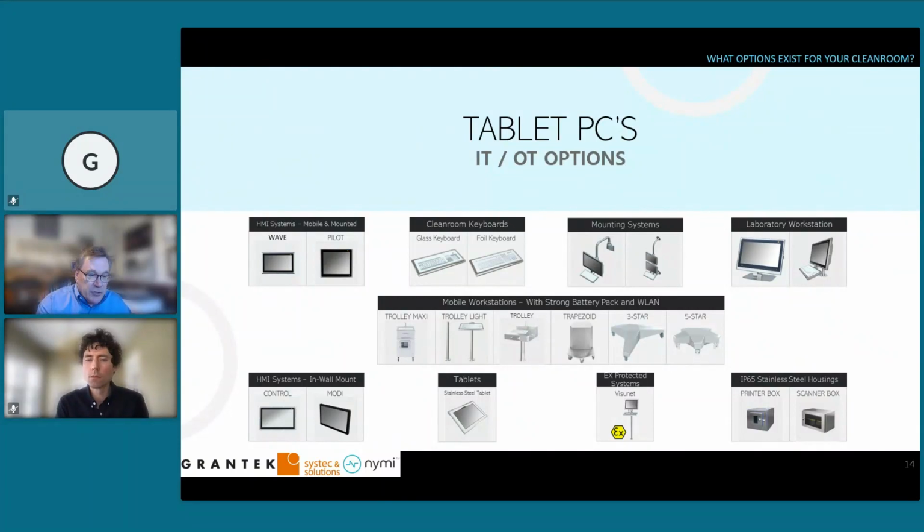First, you have your screen and your IPC, and they can be anywhere from 7-inch diagonal up to 55-inch diagonal, wrapped in stainless steel, proper glass, proper sealing, ready to withstand any washdown from a 1.9 pH spore cleanse to a 12 or 13 pH, 40% sodium hydroxide, isopropyl alcohol, purified water, etc.